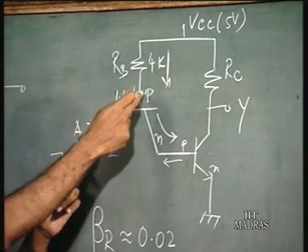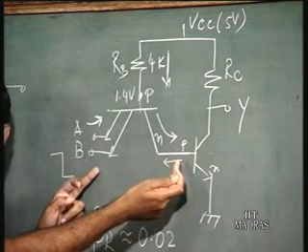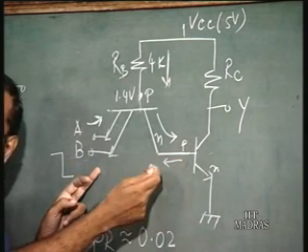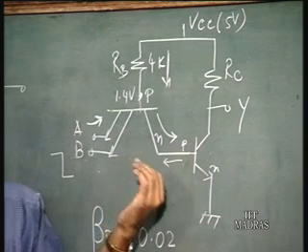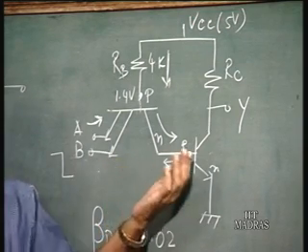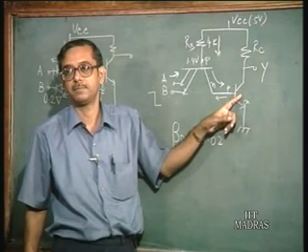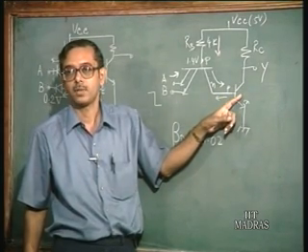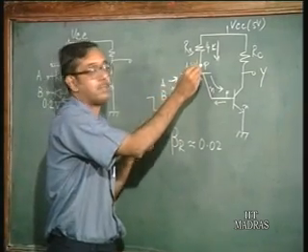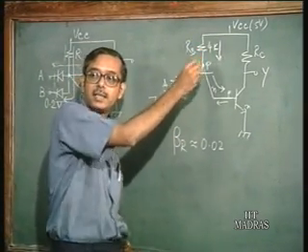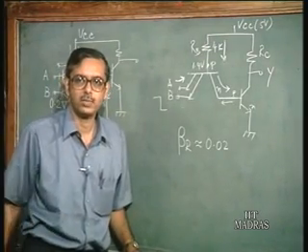So there is a base current flowing in, and so there will be a tendency of a collector current flowing, and this collector current, what is it doing? It is removing the stored charge, base stored charge of this transistor. Suppose we have seen if this is 0.2 volts and this is 0.9 volts here, the base current is 1 milliampere, slightly more than 1 milliampere.